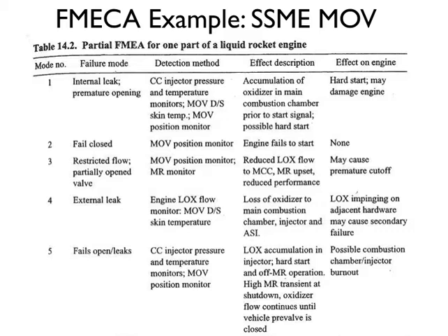One note about that though, I don't particularly like the way they've done it here, and I think it could be better. The note I'll make about that is that one of the most effective ways I've seen this done is to list the mode number by the subsystem that it's in, and then by a number. So essentially what I think they're missing here is a subsystem. And that's important because when you think about how many lines there will be at the end of the day in the FMECA, it could be thousands, many thousands.